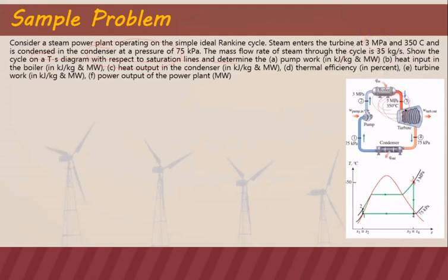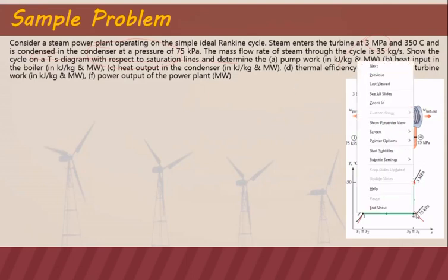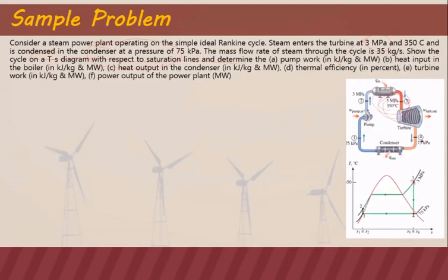And then it enters the turbine, and in the expansion process, it reduces both the pressure and temperature, and then it's at 75 kPa now on the condenser side. At state 4, that is 75 kilopascal, and then it enters the condenser where, from a high quality mixture, it becomes saturated liquid.